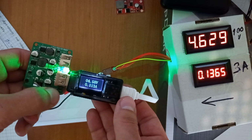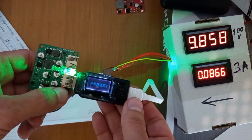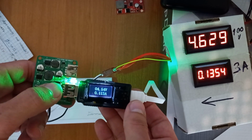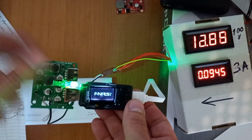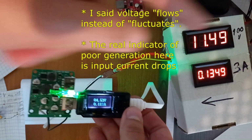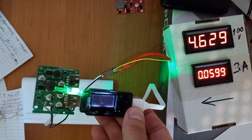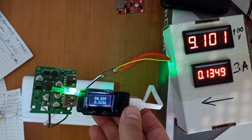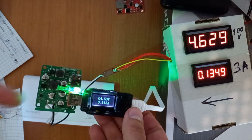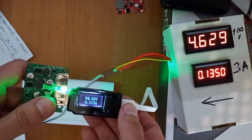So we connected to a QC port. It attempts to perform a handshake. It fails to raise voltage and everything reboots, and during this phase voltage flows here and there, and you cannot track it fast enough, but you don't even generate power a lot of the time. So it just doesn't work with QC, and I assume the same would happen with a lot of QC ports.